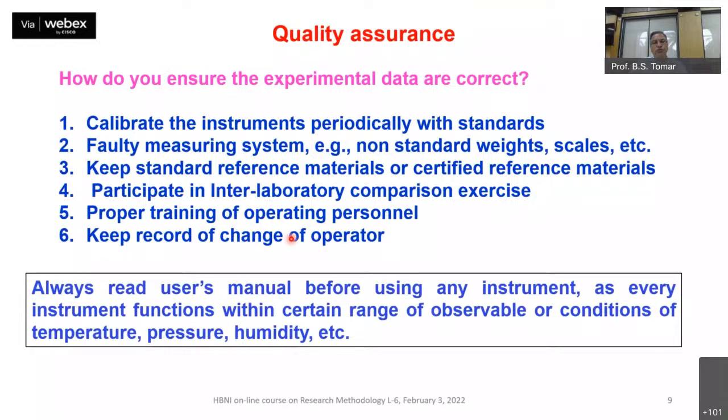Whenever a new operator comes, you should train that person properly. Keep a record of the change of operator. Sometimes systematic errors may creep in when you have a change of operator, and the new operator may not be as trained as the previous one, or may have their own biases. So these are the important aspects you have to keep note of.